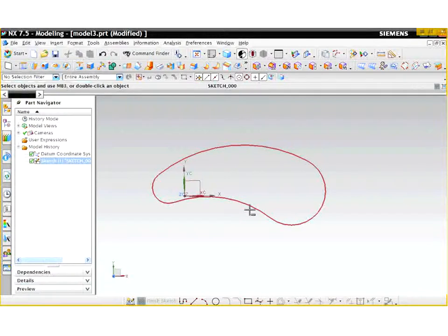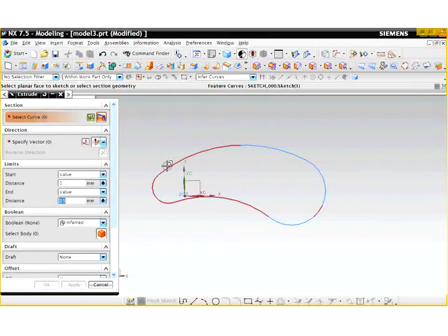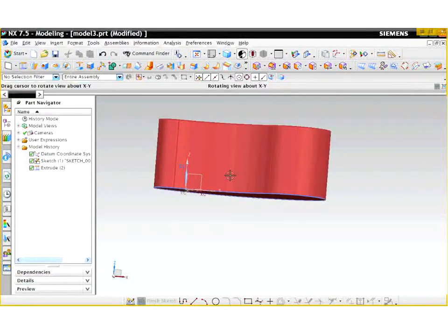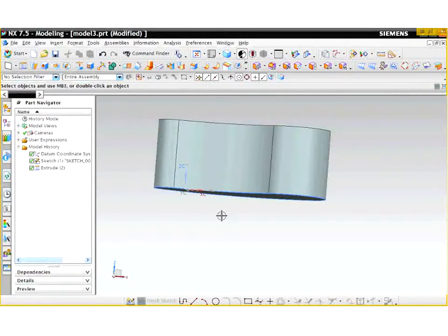What we'll do is we're going to extrude this shape, and we can extrude it some distance that we choose. I don't know, let me say 50 millimeters we can extrude it by. Okay? And what we're going to do is, below this axis, we're going to create another type of plane that's a curved plane, and we're going to use that to cut this particular body. And when we cut the body, we're going to end up with the shape